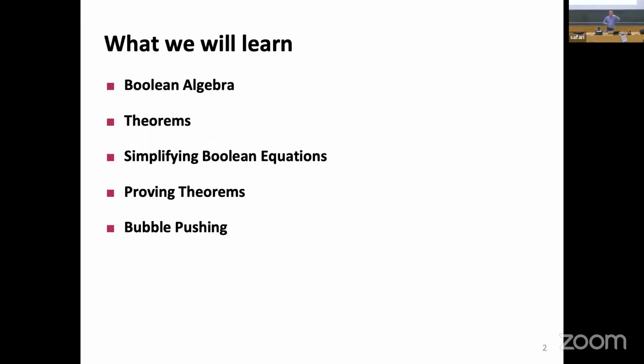Yes? Money. Excellent. You are my guy. Money. In terms of building integrated circuits, the thing that really costs money is how many of these things you need to manufacture. The more functionality you have to pack, the more area you need, and you pay per area. If you need 1 million of those, you pay 1 cent, and if you need 10 million of those, you pay 10 cents. So money equals the area.